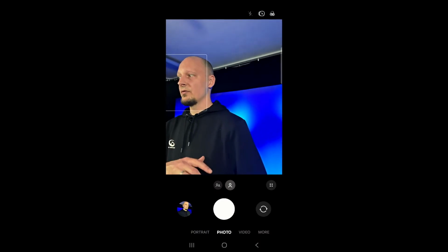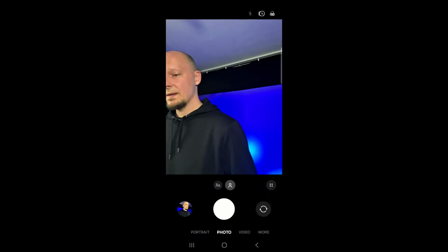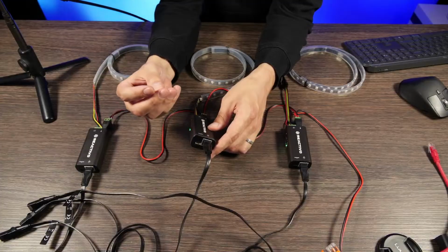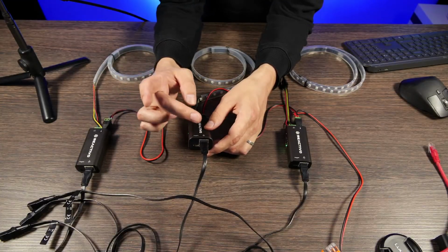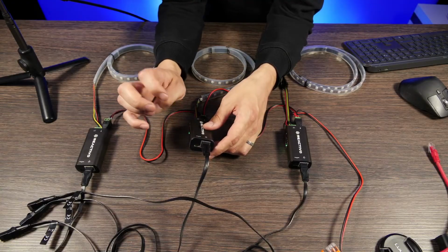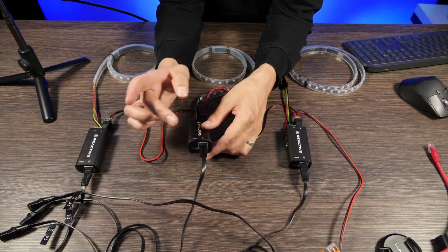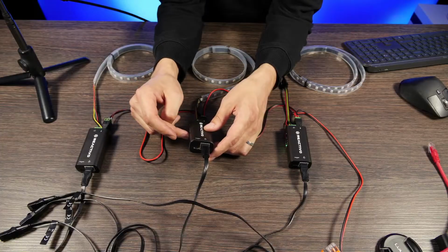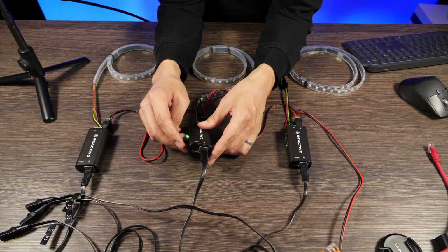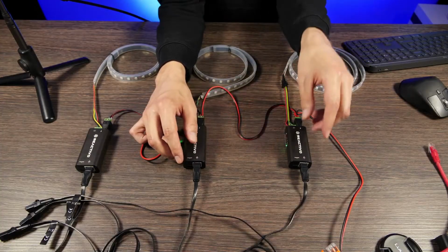So these are the two options if you want to use the wired connection, that is an Ethernet cable. I will just once again mention that with the controller, although it has an Ethernet port and also a Wi-Fi module, you can't use both at the same time. So you can only use either an Ethernet cable or a Wi-Fi connection. If you wanted to, it's not really an option with this device.